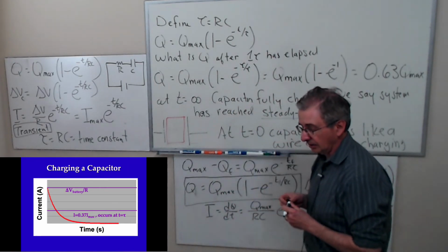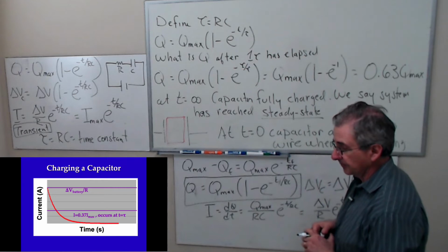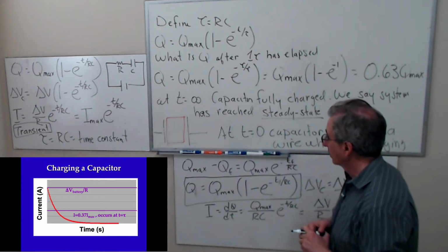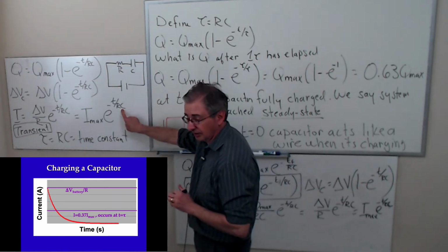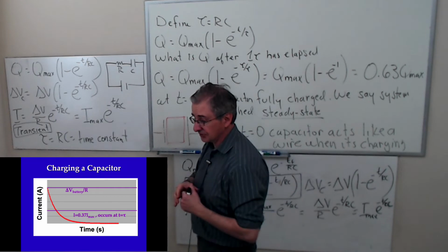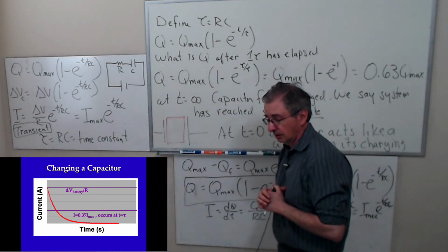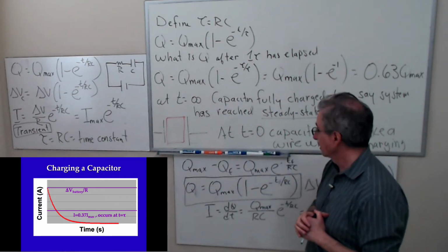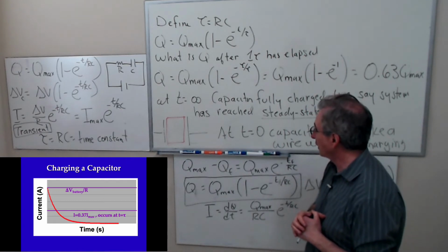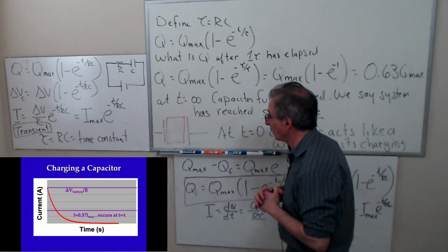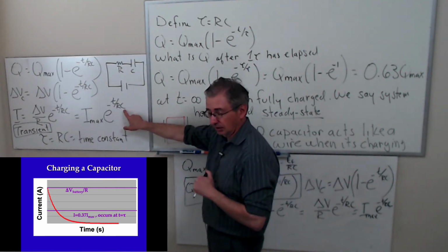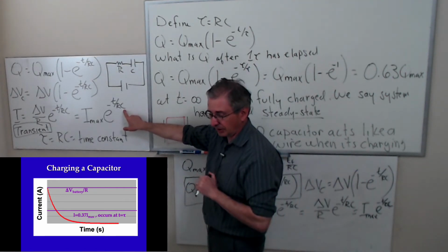Does having a dielectric there increase the amount of time or decrease the amount of time it takes to become fully charged? Well, that's going to increase C though, right? So it'll increase the time. It'll make your time constant bigger. I see. So if you want to block DC and let AC through, you probably want this to be fairly small. Of course, it depends on the application, right?